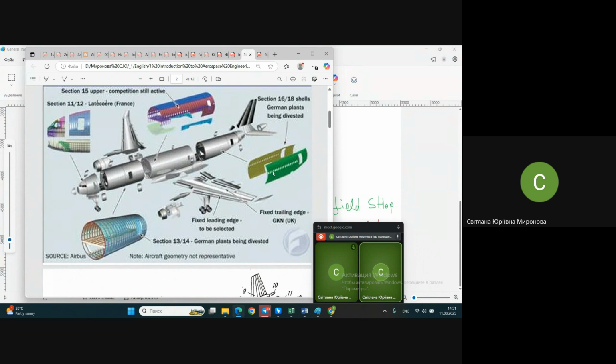So this differentiation of assembly work into different working stations has a lot of reasons. One of these reasons is shortening the general time of assembling due to paralleling of the work. Another reason is that it creates conditions for flexibility of the work, for increasing the automation level of the work. And by this, it more probably increases the quality of the work. Another important reasons might be something you will study when you study assembling, but the general idea is that the differentiation degree is deeper and it's better to deepen this differentiation degree, to increase this separation of the airplane structure into pieces while assembling. It's better, but it's a balance of this better with the cost of this better.